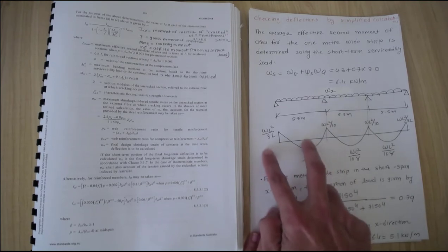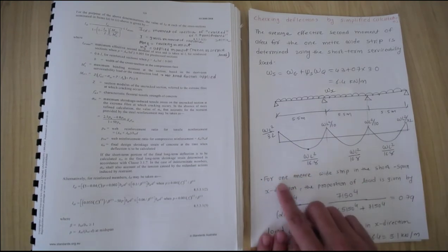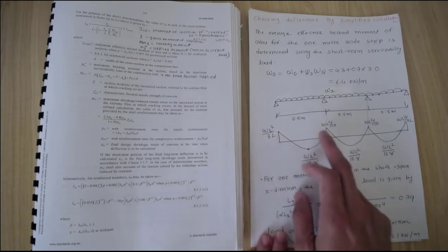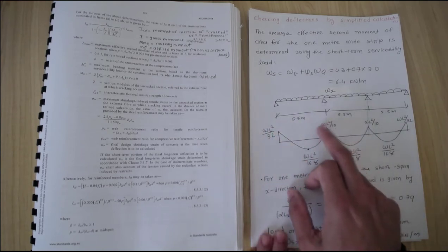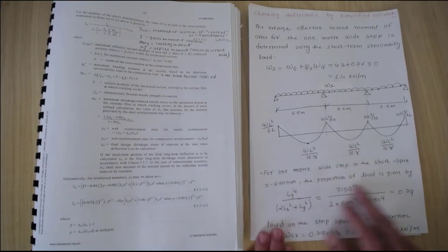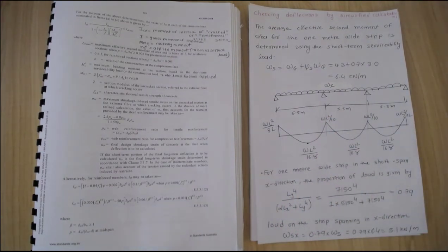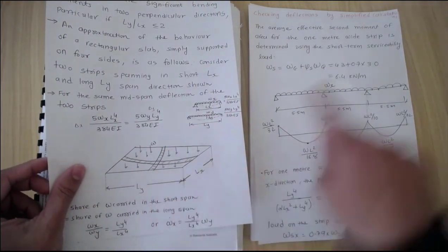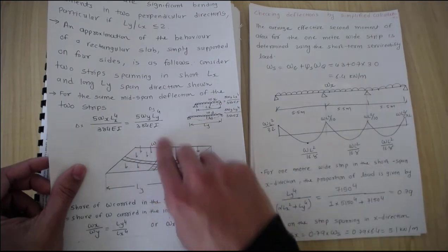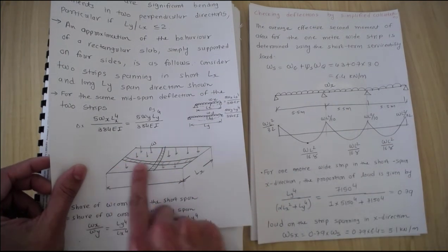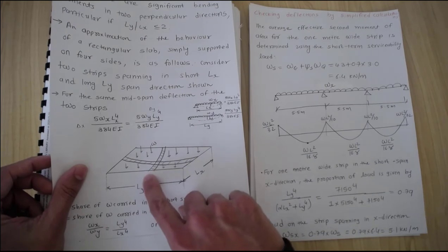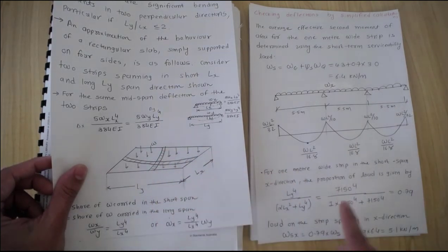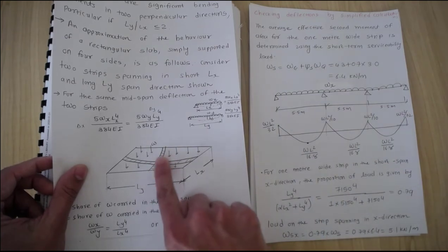I'm not going into the detail of structural analysis, but for a 1 meter wide strip we will have, at the left support, WL squared over 32, then WL squared over 16.8, and WL squared over 10. We need to know what proportion of the load is carried by this X strip. You can see the total load is 6.4 kilonewton per meter. That is the total W load coming, but the Y direction will carry a proportion of the load, and this strip will also carry some load. So we need to calculate the amount that this strip is going to carry.